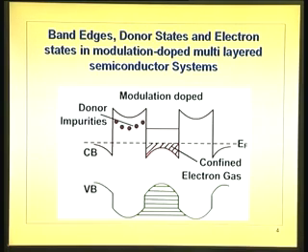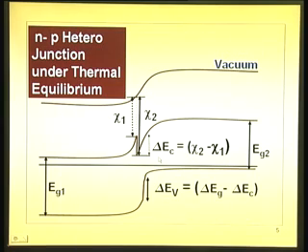Now, how thick you want that layer is decided by where you want the energy for a multi-layer structure. But in this particular case, where you have only 2 layers, all that you are looking for is this notch, which is created by this. In fact, we have shown last time how to generate this energy band diagram for the aluminum gallium arsenide layer.